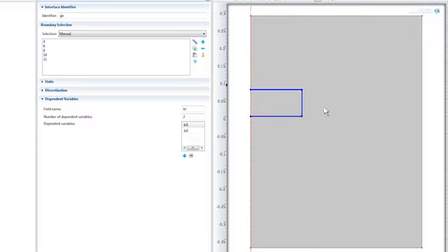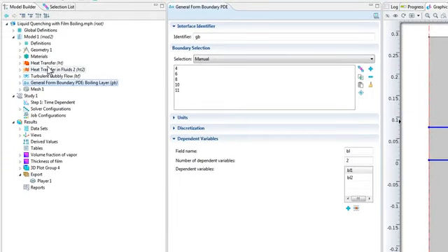The boiling layer thickness, which of course in real life has a finite thickness, will not be explicitly modeled. Instead, the boundary PDEs approximate the mass, momentum, and energy transfer in the boiling layer. COMSOL's custom PDE interfaces available with the base package easily allow for these equations to be coupled with the conjugate heat transfer physics. Let's take a few minutes and go through an overview of how this model was set up.